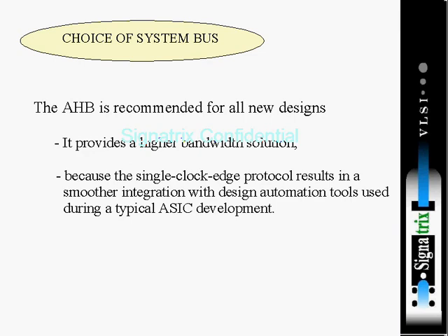If you are using event based simulator, it will check the events. Whenever the change is in A, it will trigger the block B. Okay, so during that time it will come and evaluate that B signal, and it will give the result of that B. This is event based simulation. But in the case of cycle based simulation, that simulator will work with reference to one clock. Okay, so in every edge it will come and evaluate that signal.